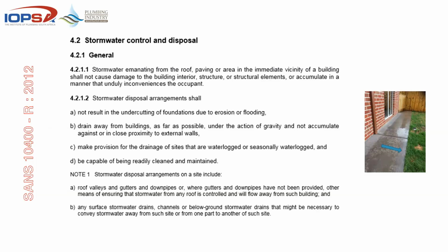So if you're staying in an area that is known for wet patches and just general soggy soil, there are requirements that you need to make provision for drainage on that site before the building is erected. In other words, you can't put a foundation in there knowing that the concrete is going to be kept soaking wet, and ultimately the steel in that foundation is going to end up rusting, etc. So you need to make provision for that drainage before it starts causing damage. It needs to be capable of being readily cleaned and maintained.